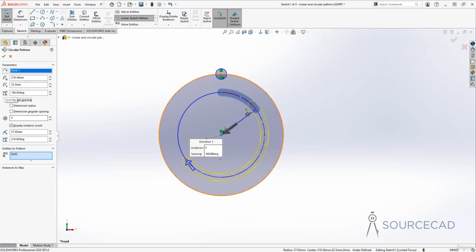and press Tab key. Now it is filling your objects along the semicircular path only. So if you connect any corresponding points, for example, the center of this slot with the center of last slot, this will make a 180 degree angle. We want it exactly along 360. So I'll type 360 and press Tab key. Now this is actually the angle which your line, this line is making currently in the array, which is 216.80 degrees from this exact point. So if you make a straight line like this and then start measuring the angle in anti-clockwise direction just along this,